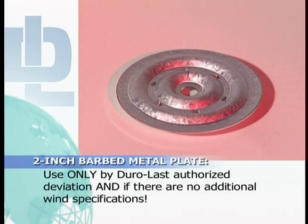If the membrane is going directly over a hardened surface such as concrete, wood, or built-up roof with proper slip sheet, you can use a 2-inch barbed metal plate only by Duro-Last authorized deviation and only if there are no additional wind specifications on the project.